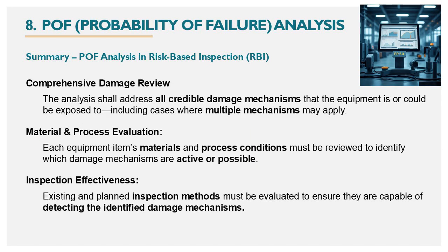Agenda number 8 is probability of failure or POF analysis. This section covers how we estimate the likelihood of failure, using factors like degradation rates, operating conditions, and historical performance. Summary of probability of failure or POF analysis in risk-based inspection or RBI. The first is, comprehensive damage review.